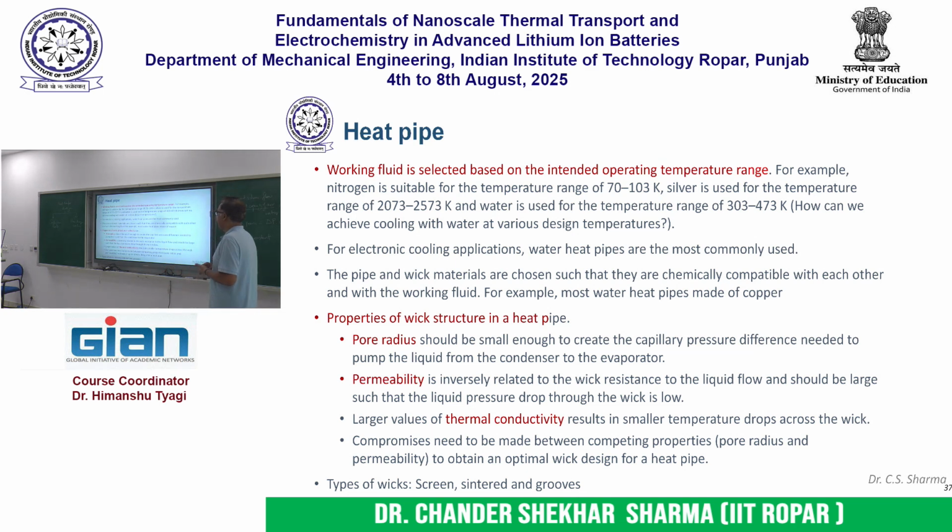When we design the wick, there are a few parameters that we take care of. One is the pore radius, meaning the size of the individual pore of the wick, which decides how much capillary pumping is available for pumping of the liquid. Then the permeability of the wick governs how much pressure drop the liquid will experience flowing through the wick.